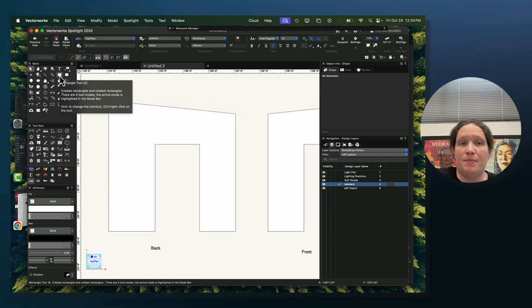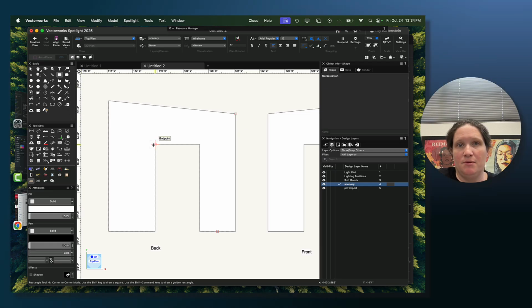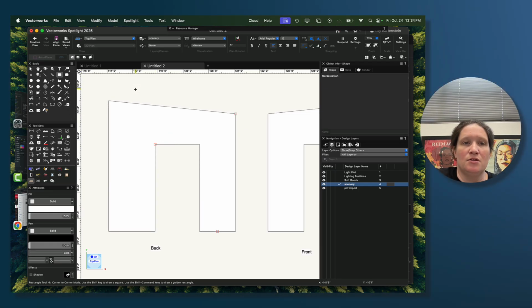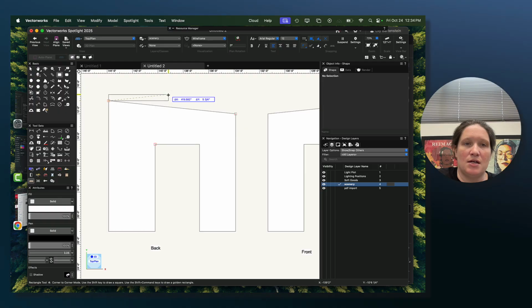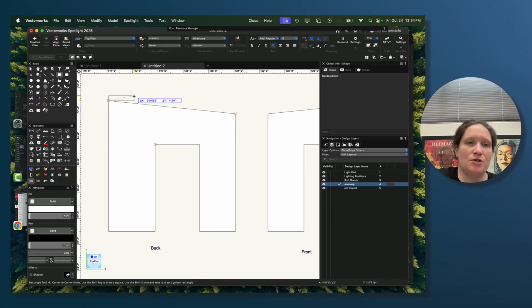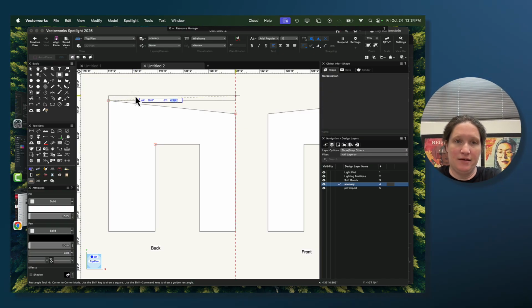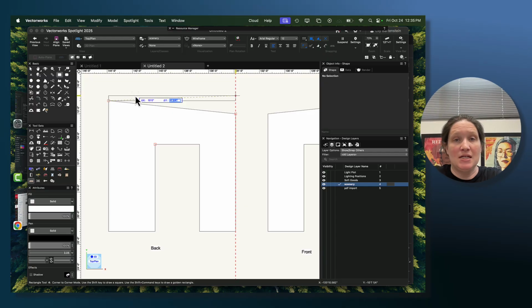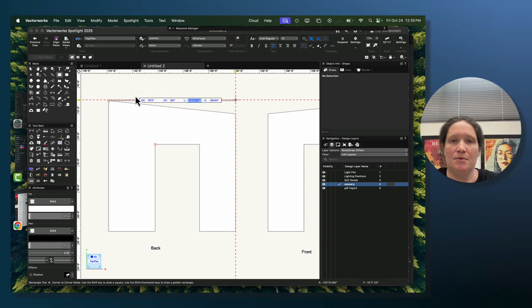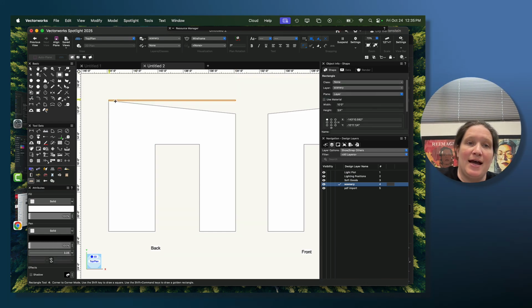So I'm going to start by putting in, with little rectangles, some of my framing pieces that I need, okay? I'm going to start with a piece that goes all the way across that middle section. I'm going to start by snapping into that corner, and then I'll move it to the place that I want it to be in the project. So it's going to be 10 feet long. I know that. That's the X length of it. And the thickness of it is the 1x3 on edge. So it's going to be 3/4 of an inch thick. Hit tab, click, okay? Now I have this piece.